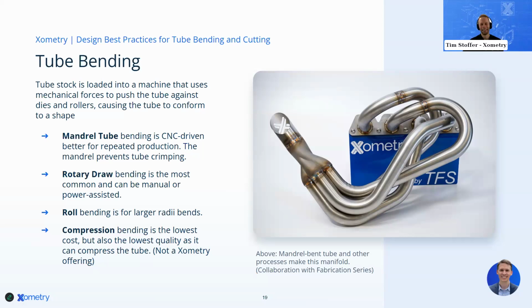And the thing that we're avoiding though is compression bending. I always describe compression as like if you're taking a straw and bending it with your thumbs, you're going to see that pinch point in that design. All of our bending is done in a way where we're looking to preserve the circularity or reduce ovularity, if you will, of the design in its final state. So we want to hit your CAD, essentially, is what it comes down to.